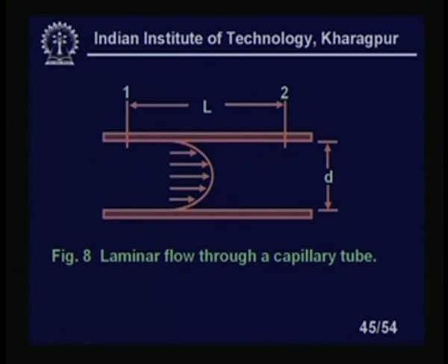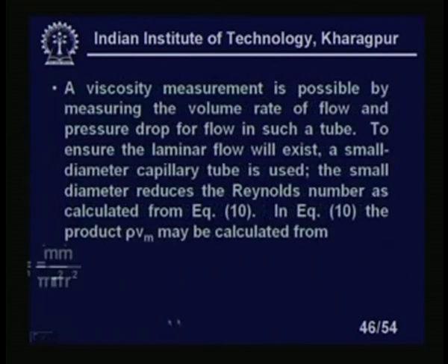You see here the velocity distribution of the laminar flow. The liquid is in contact with the inside pipe diameter, there is no motion there, and here you will find the velocity is maximum, okay, at the central point. As it goes towards the wall, the velocity of the liquid which is in contact with the inner surface of the pipe is zero. So, this is the velocity profile of a laminar flow of a liquid inside a pipe, right. We are talking of Vm, that is the average velocity, measured at separate points and then averaged.